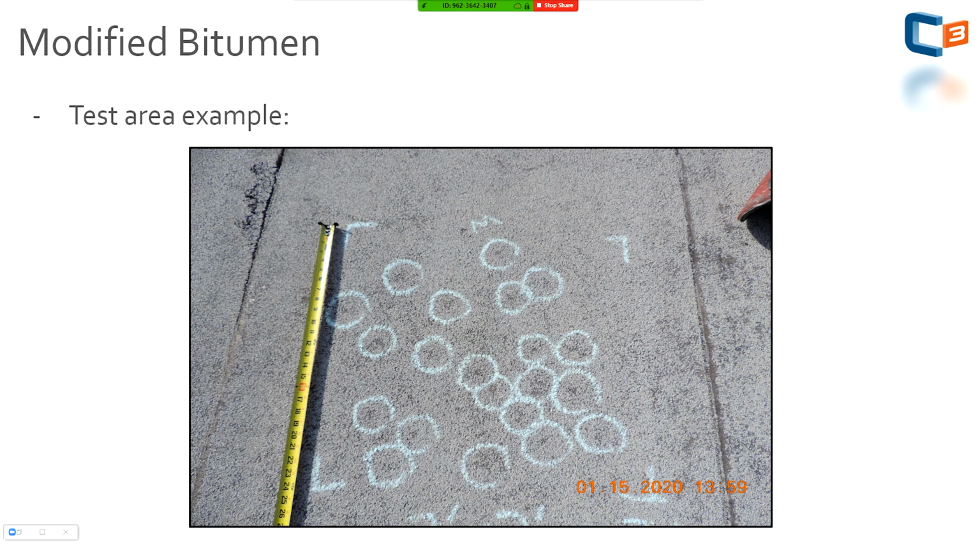So that's ethylene propylene diene monomer. What a mouthful. And it's an elastomeric synthetic rubber. So this can be reinforced or non-reinforced. If you look at the left side, it's very smooth. And then on the right side, you can see that scrim in there. So that's a reinforced product. Generally, we'll assess these the same exact way. This is a thermoset roof system.